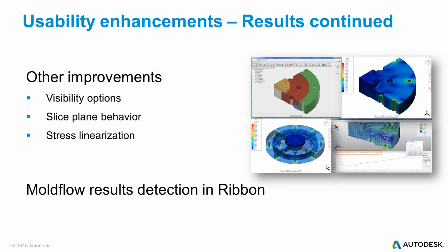And if you have isolated a part, or a couple of parts, you can simply right-click on the canvas and say Show All to show all the invisible parts with one click.